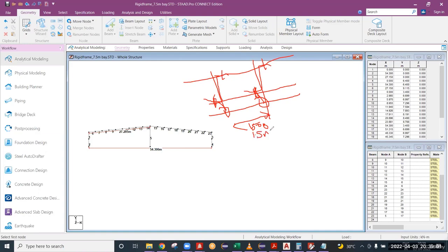I'm telling you now, it is not writable here. I cannot write properly here, because it is drawing like this, right? That is why I cannot write properly here. To show you, it is 1.5 meter. Purlin spacing: you cannot provide 150 mm because the flange itself comes around 65 to 100 mm. So you cannot provide side by side purlins like this. It will get clumsy and it will give much more weight.